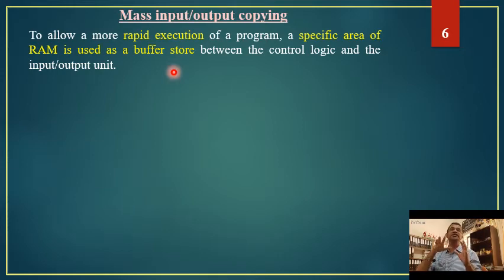only to retain the inputs that are coming from the sensors, and the outputs that are required to be processed by the PLCs. Now note that in the first instance itself, all the 1000 inputs are coming. Whereas in the previous case, in one instance, first sensor is sending the data, second instance, second sensor is sending the data. So for 1000 sensors, 1000 instances are required. And that also involves 3 milliseconds of delay every time.